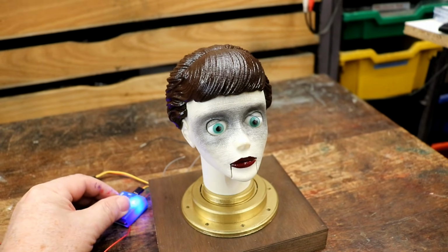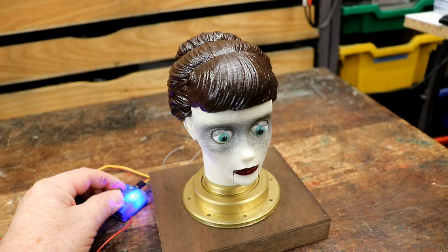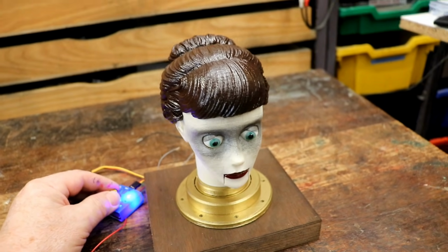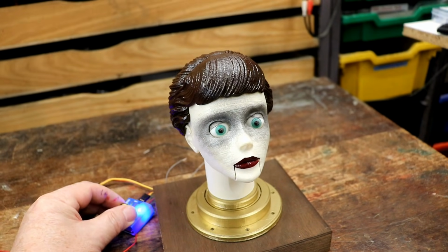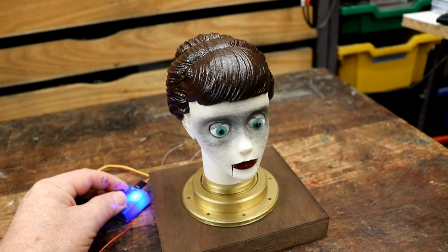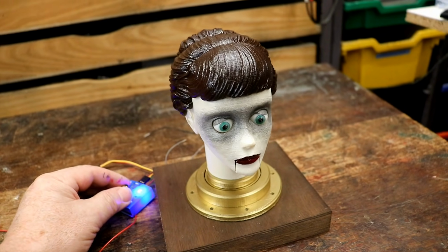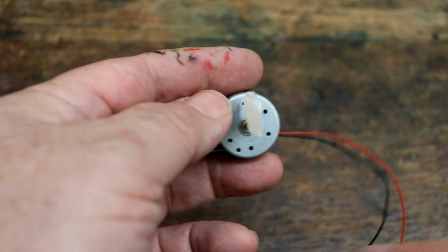Now we want them to move slowly because servo motors are designed to move very, very quickly from one position to another. We don't want that because it'll look silly and also put lots of strain on the mechanisms. So we need the servo motor to move slowly, and I'll explain how to do that when we come to programming. But it is possible. You can see I've been using Sharpies to draw with.